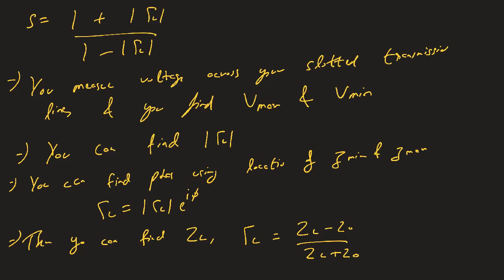So the reason that I chose this particular application of slotted lines and the voltage standing wave ratio in this short amount of time that we had to study transmission lines is because of the physics of standing wave formation, and the idea that in most general transmission lines you have back reflections at the termination point, and those back reflections propagate back and create some level of standing waves within your transmission lines.